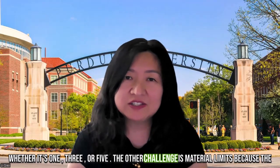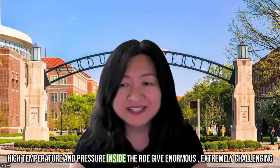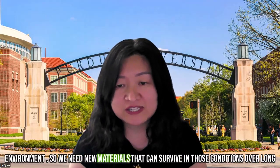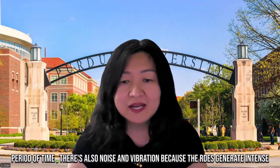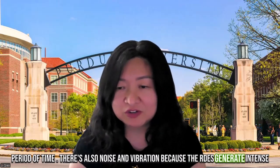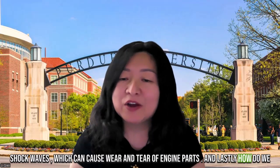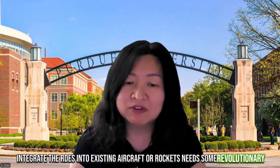The other challenge is material limits, because the high temperature and pressure inside the RDE create an extremely challenging environment. So we need new materials that can survive in those conditions over a long period of time. Also noise and vibration, because the RDEs generate intense shockwaves, which can cause wear and tear on engine parts. And lastly, how do we integrate the RDEs into aircraft or rockets? That needs some revolutionary thinking.